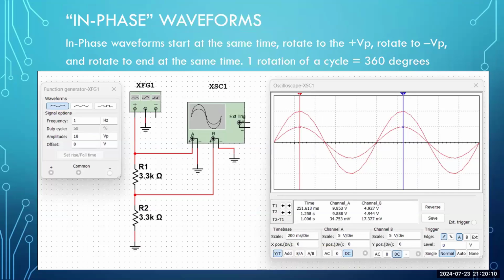There we go. I want to show you waveforms, two traces in this case. And what I have is a simple voltage divider. The simple voltage divider is not set up with the DC source. I'm setting this up with a function generator. And the function generator generates different waveforms. It generates sine wave, square wave, triangular wave, different kinds of waveforms. And so what I've done is I've set this up to generate sine wave.